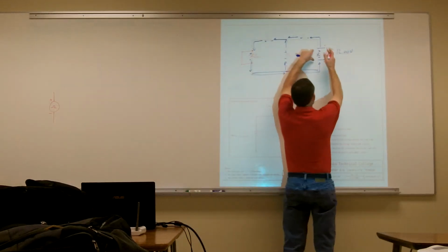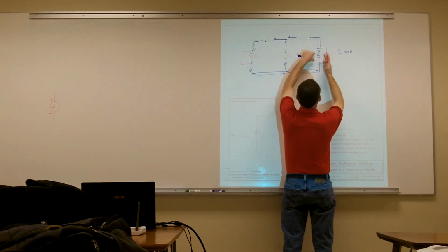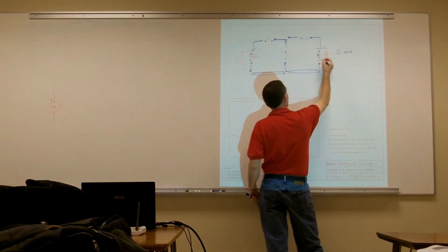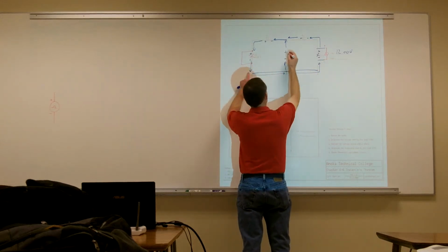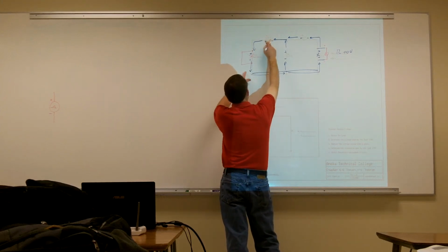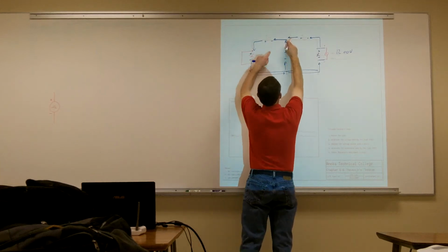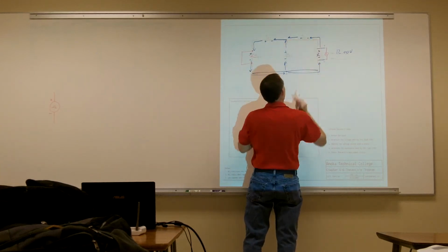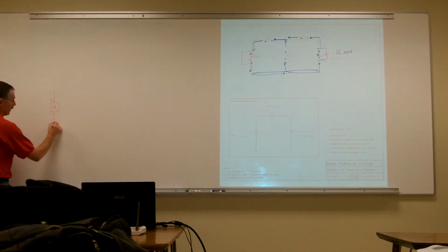So when I'm looking at this, I'm trying to figure out what type of configuration I have now with my power supply being shorted. So now my current is going to come down out of my ohm meter, come through my grounds, and it's still going to split up. Some of it's going to go through R2, some of it's going to go through the power supply that's being shorted out, through R1. Those two currents are going to combine, and then all the current is going to go through R3. So I'm just going to re-sketch that out.